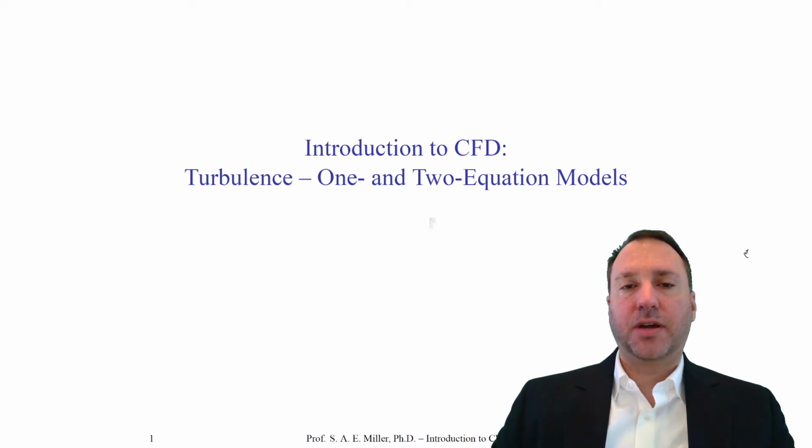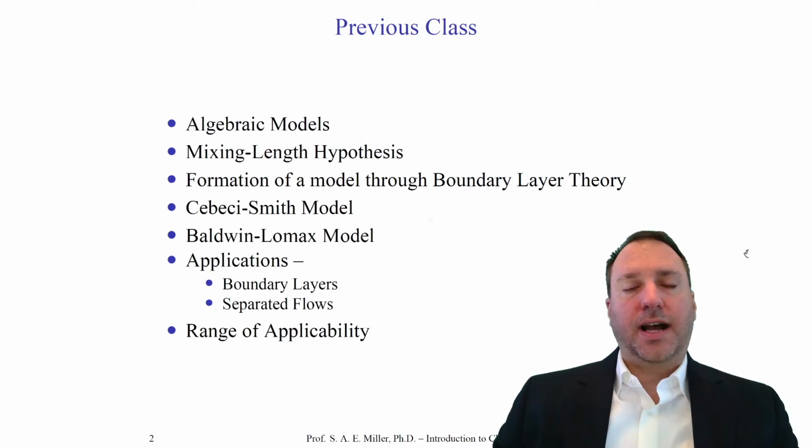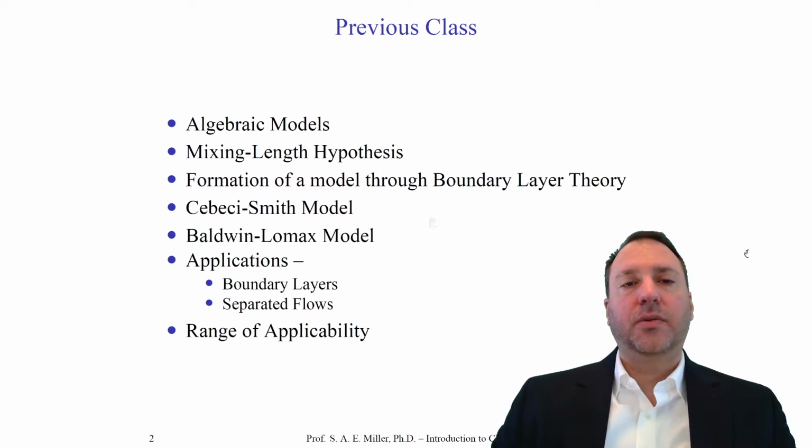Remember, the purpose of these models is to close the equations, and we need to make the number of equations equal to the number of unknowns. In the previous class, we looked at particular algebraic models, perhaps seen as the zero equation models. We introduced Ludwig Prandtl's mixing length hypothesis and reviewed the formulation of one of the most famous and historic models, the mixing length model based on the Prandtl mixing length hypothesis. We looked at the formulation for a boundary layer turbulent flow.